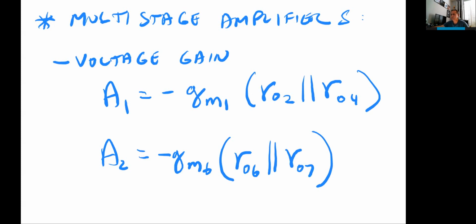a common source. So the gain for A2 is going to be from a common source loaded with a PMOS current source. So again, going back to the actual schematic that this expression is referred to, let's look at it.